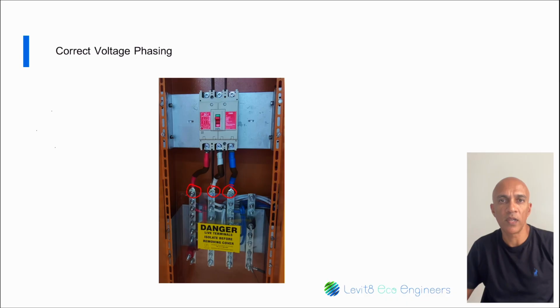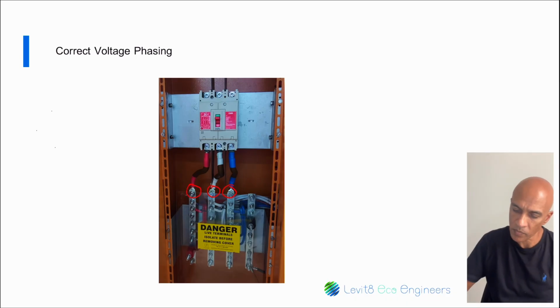If you are measuring quality of supply specifically, there are instruments designed specifically to measure to the known quality of supply standards. In South Africa, we have the NRS 048 series of specifications with specific measurement requirements which define the sampling rates and averaging of data, including the reporting for specific periods. There are a number of instruments that are made to measure in accordance with those exact specifications and output reports in the NRS 048 required formats.